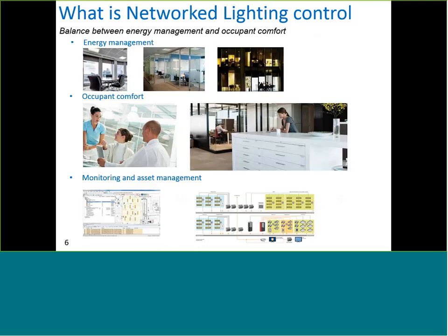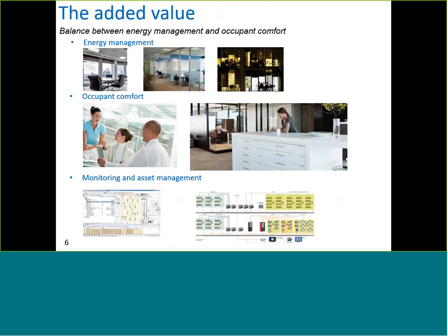The way that we add value to the office segment, we can break down into 3 areas: energy management, occupancy comfort, monitoring and asset management. One of the biggest focuses we've had for the last 10 years has certainly been energy management. And through the mixed use of scheduling and presence detection, we're able to achieve a majority of these goals. So with scheduling, we can simply turn the lighting on and off when moving between trading and after hours. And then with presence detectors, we can make sure of finer control, shutting down areas which are no longer being used.